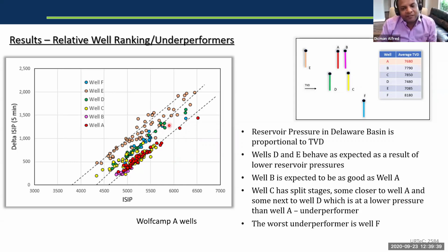But one thing I can tell you is, if you see this plot, let's assume you have an E well, D well, and A well. You have the luxury of opening up your choke. When you actually do the flowback, you have the luxury of doing a different choke strategy on well A compared to well E. Most people do not like to change the choke strategy, but use this plot and go back and say, I got enough pressure to play with.